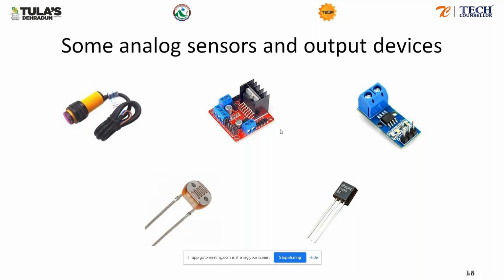So I'll hook up this particular module, the red one, and I will give it a PWM signal, which is again a type of analog signal. When I give it 5 volts, the motor runs at full speed. I give it 0 volts, the motor does not run at all. I give it 2.5, the motor will run at half the speed. It's like a linear interpolation: 5 volts represents the full value, 0 represents nothing, and all the values in between represent whatever the ratio comes up to.